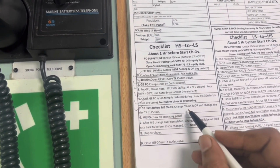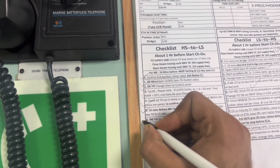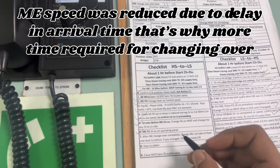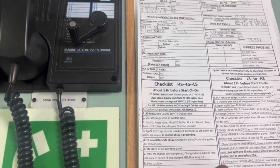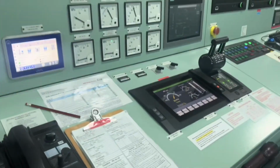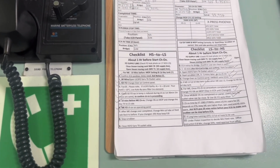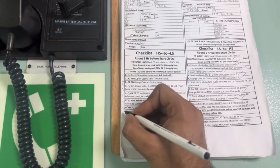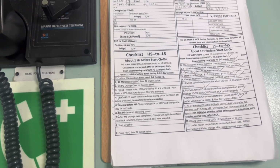So sulfur content was changed, and from the panel in the purifier room, the changeover was done. So it will take around 6 hours, and then what we need to do, we have to stop the scrubber. So this will be done in the morning, 6 o'clock. Now it's almost midnight. So it will take around 6 hours just before the ECA in. So 30 minutes before entering the ECA area, we will stop the scrubber, and then changeover will be completed. So we will wait for this. So by the time, take rest.